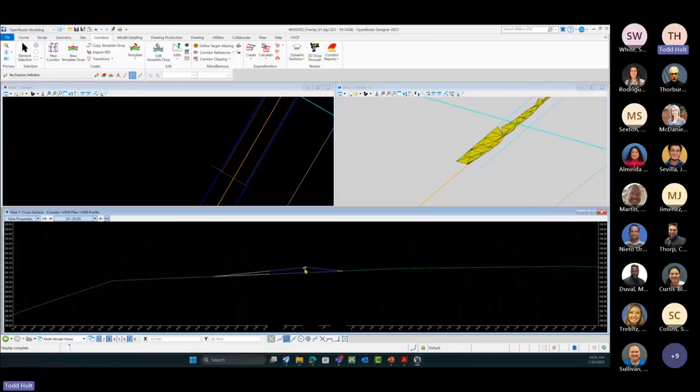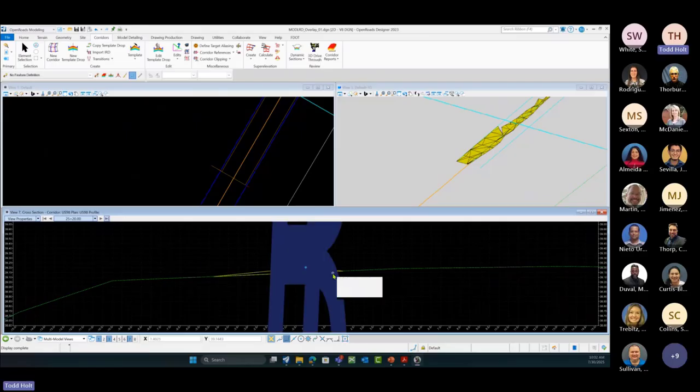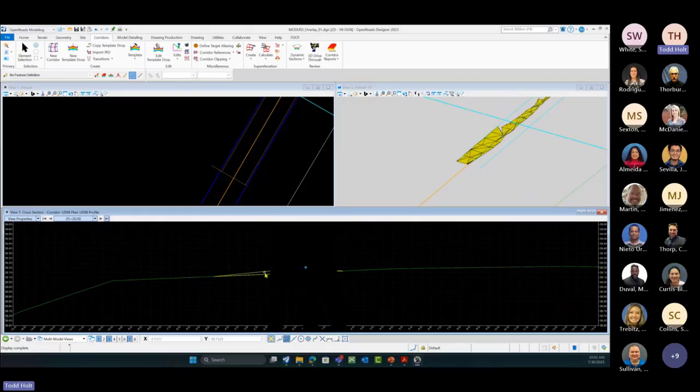If we change and raise that elevation just a little bit in there as well. All right, so we're seeing that if we're going to mill that back in, we need to have this much overlay to correct that slope. So we have that cross slope correction or the different multiple overlays in there. All right, does that make sense to everybody? Any questions on that, the milling component? Or the overlay component. All right.